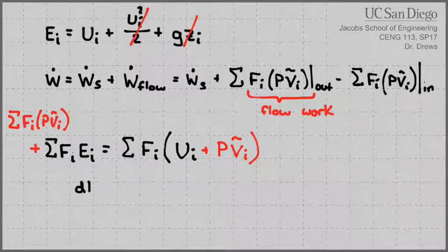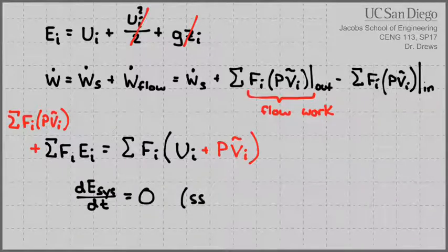Another slight variation is that the energy of the system with respect to time is always going to be equal to 0. That couldn't be the case with a batch reactor. If that was the case with a batch reactor, then we were essentially dealing with an isothermal system. But the only way that energy changed with a batch reactor was with respect to time. Here, we're less worried about how it's changing in time because we're going to assume it's steady state. It will still change with location as we go down the length of the reactor. But at any individual point along that reactor, the temperature is constant.